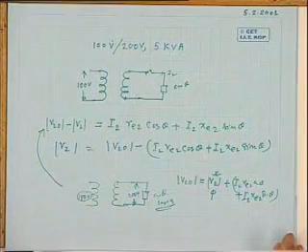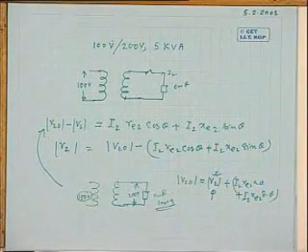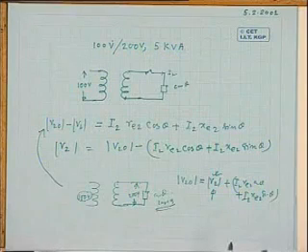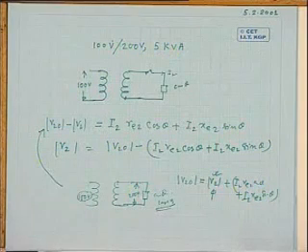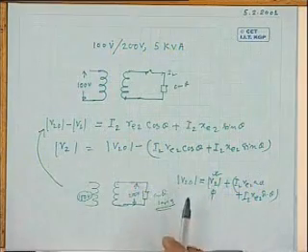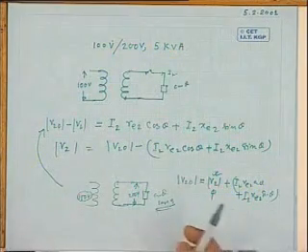Now, as we have seen that this regulation should be small, the constancy of the voltage should be maintained. Suppose distribution transformer output, so many users are connected, and it appears from this formula, if one user changes its load, the current on the secondary will change, and hence the voltage will fluctuate, is not?